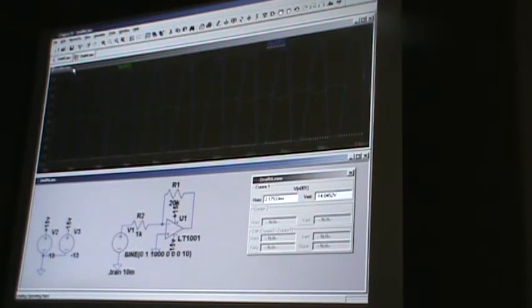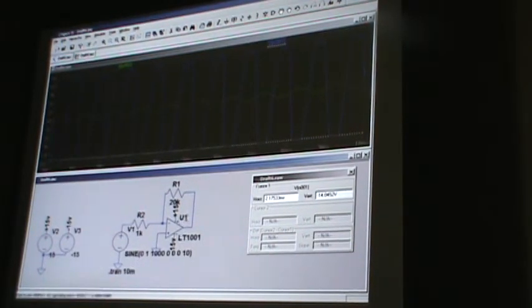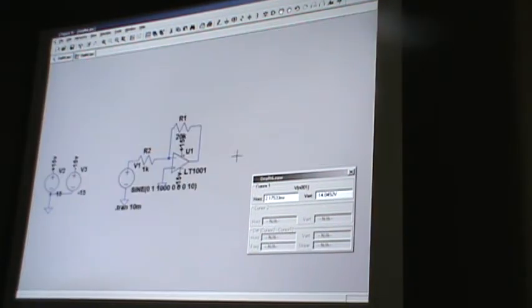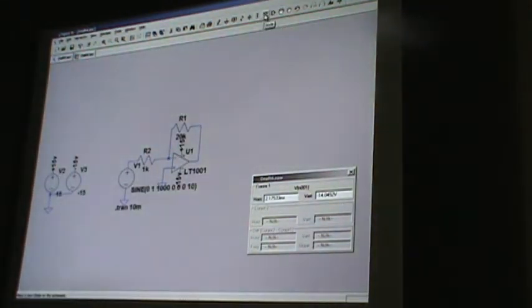But it can get more complicated than that, because there could be a dozen different models for one specific component depending on what kind of analysis you're doing. You may have one for high frequencies, another one for medium frequencies. You may have one for temperature drift, where it does a better job of simulating temperature changes in your component.